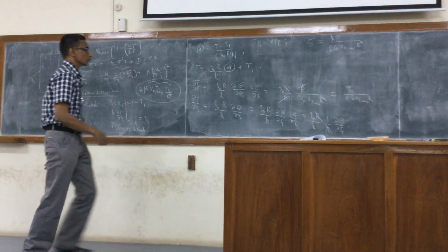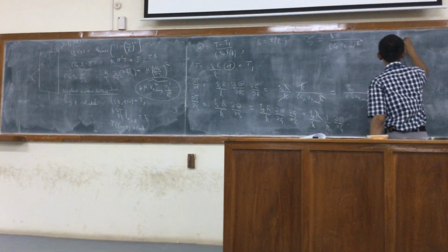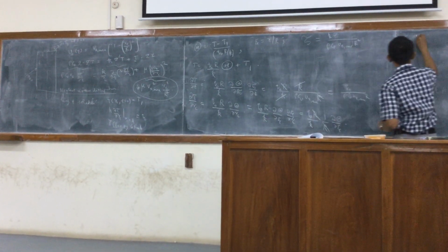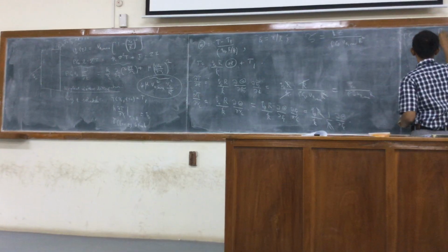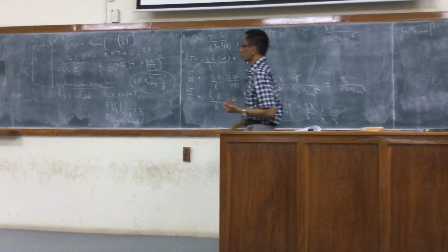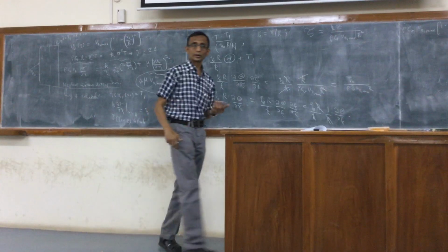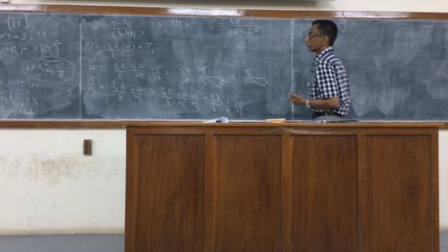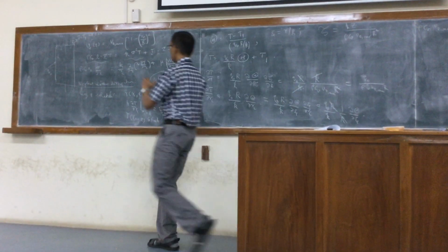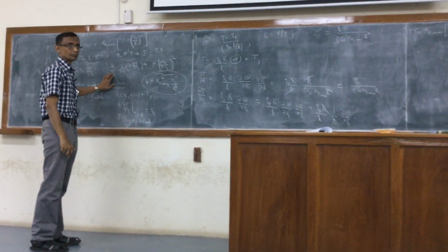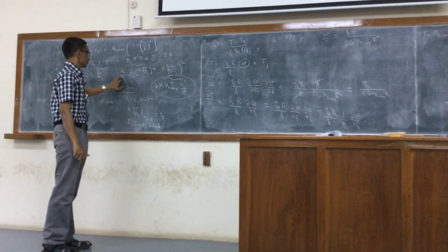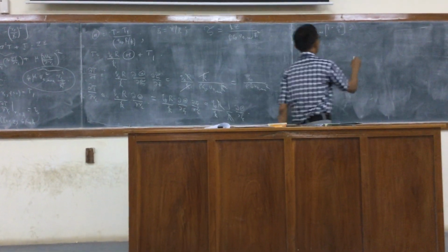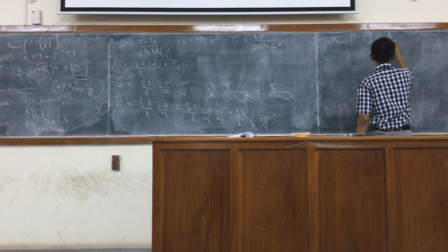So I can now start writing the equation. I get rho Cv Vz max times 1 minus rc over R squared, which would be psi squared, equal to k over rc. So k over rc would be k over R times psi.